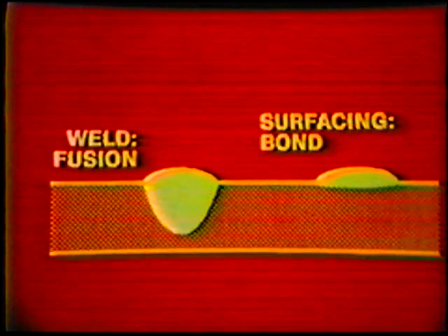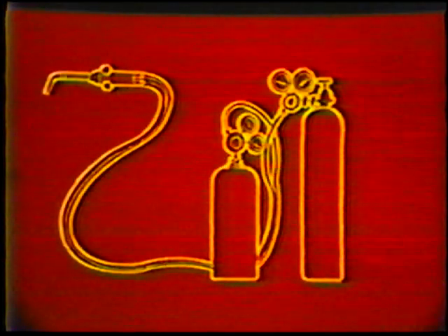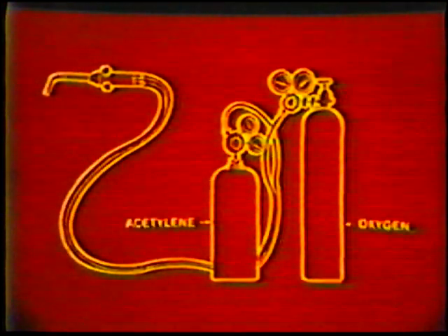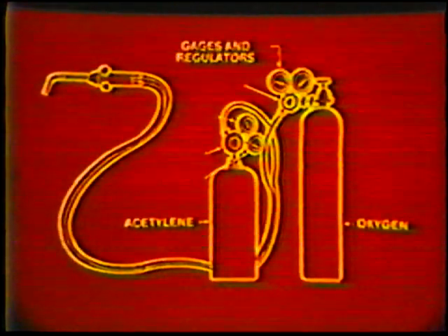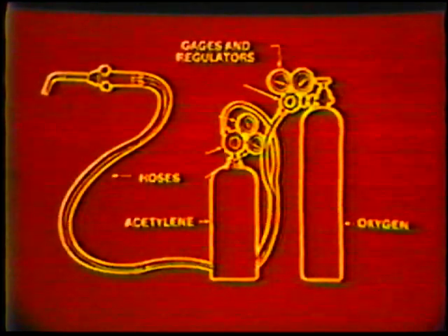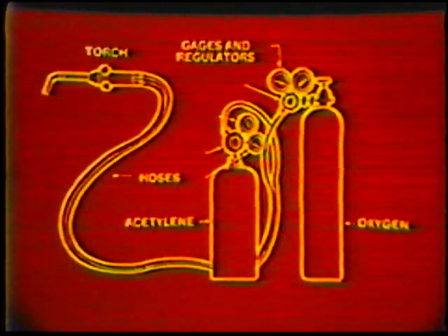The oxyacetylene flame can also be used for flame hardening, forming or bending, straightening, wrinkle bending, and flame descaling. With an angled tip, the process can remove defective welds with the scarfing or gouging application. The equipment needed for this process consists of an oxygen and acetylene supply, pressure gauges and regulators, hoses with fittings and check valves, and a torch equipped with a suitable tip for the particular application.